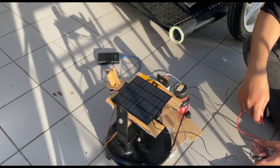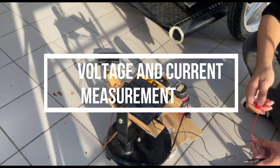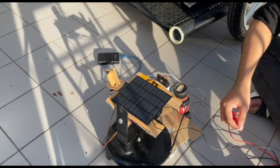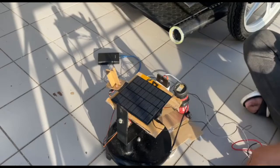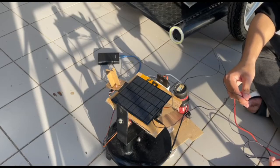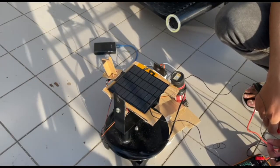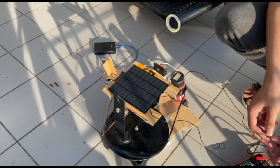To measure the voltage and current, a multimeter is used. The positive probe is connected to the positive terminal of the solar panel, and the negative probe is connected to the negative terminal of the solar panel, and the voltage will display 9 volts. While to measure the current, the probe is connected in series with the load.